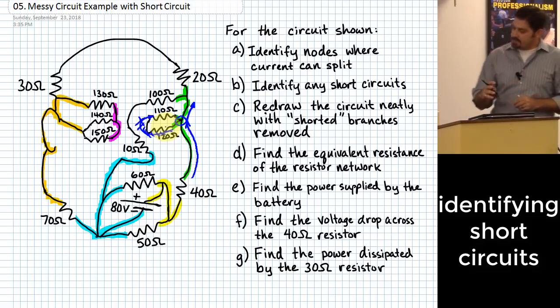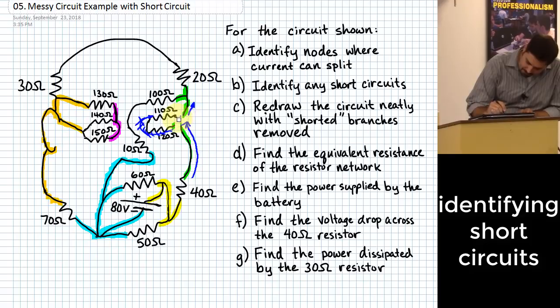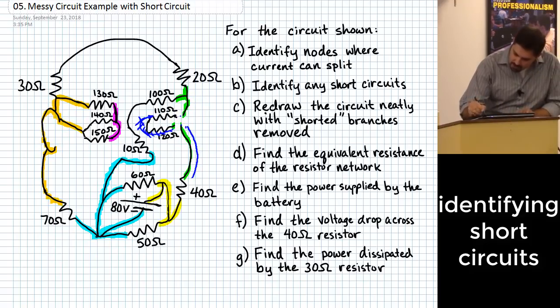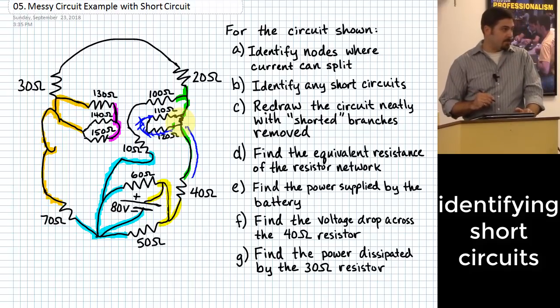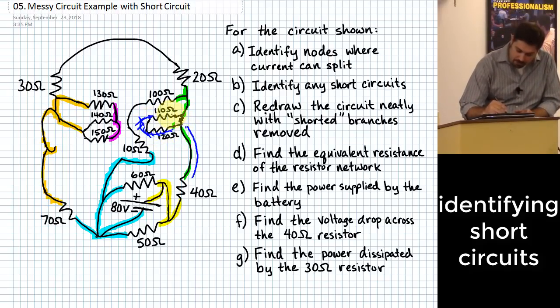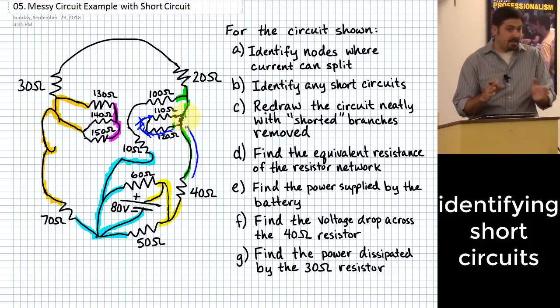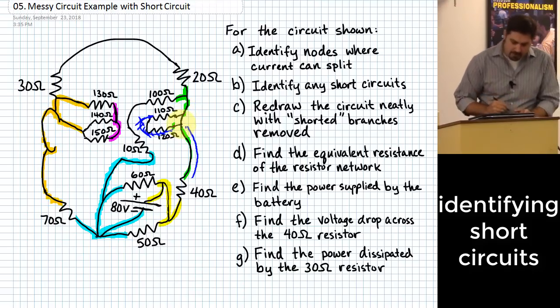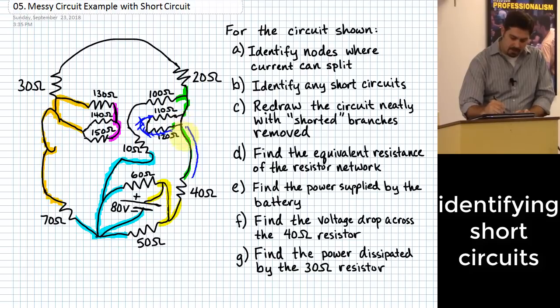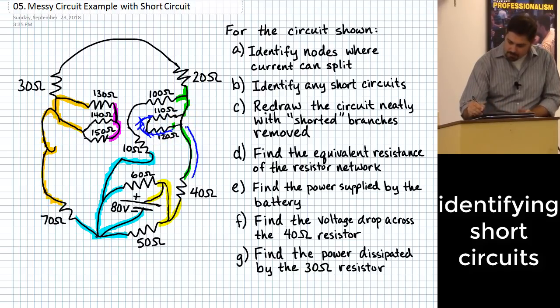I think what you're saying is if it was set up differently, right? Let me kind of change this up just a little bit. He's saying if for some reason it was set up to where there was a resistor right here, and then this went to one side and this went to the other side, changes the game, right? Because now some of the current would want to go through the resistors on the left, and some of it would go through the resistor that I just put right there. That is different. That is no longer a short circuit. But the fact that this right here basically represents just wire, it's going to take that path. There's no reason that the volts or the current is going to want to flow through that other piece.